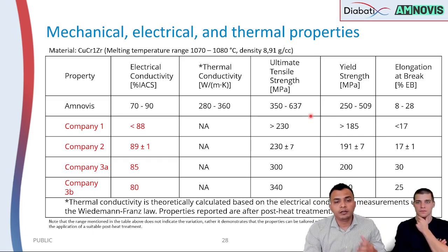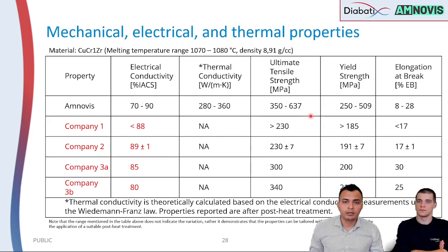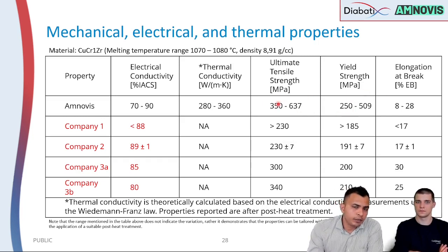And as I explained in the first slide, the combination of yield strength and thermal conductivity is important when you design heat exchangers, and not only electrical conductivity, when it comes to complex shaped parts with fine features. In addition, despite having those high mechanical properties, we also get quite high elongation. In some cases, it's beyond 20% with 500 megapascal in strength.